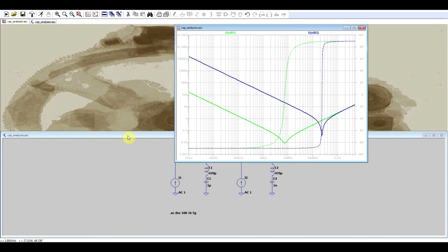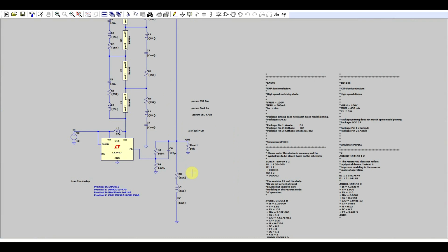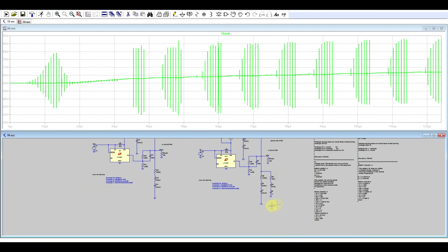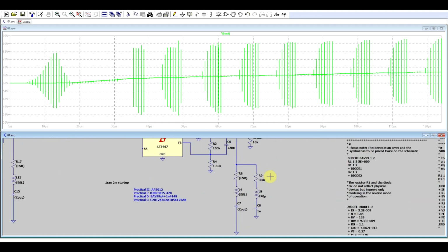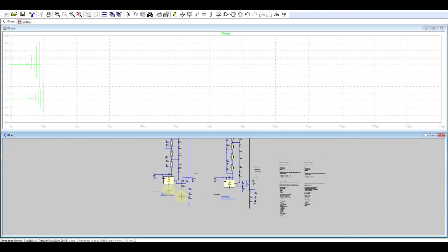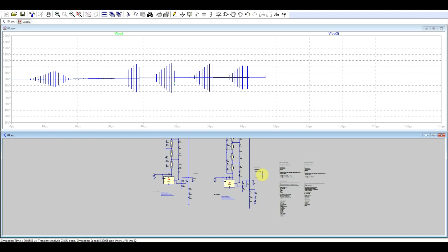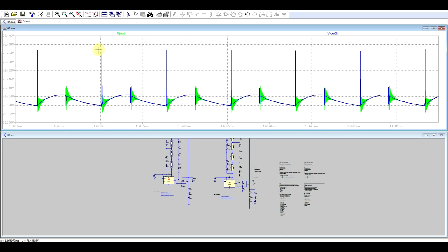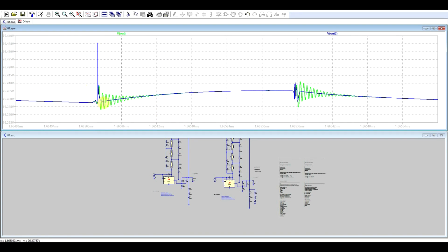So one of the things you can try, when trying to reduce the noise of your switching supply, is add some low value capacitors. So if we add the 1 nanofarad capacitor into our circuit, and compare to the circuit without the 1 nanofarad capacitor, we can see that the simulation is going very slowly since it has to calculate two very complicated circuits. But other than that, if we zoom into our measurement this time, we can see that our noise amplitude has reduced substantially, but it changed frequency.